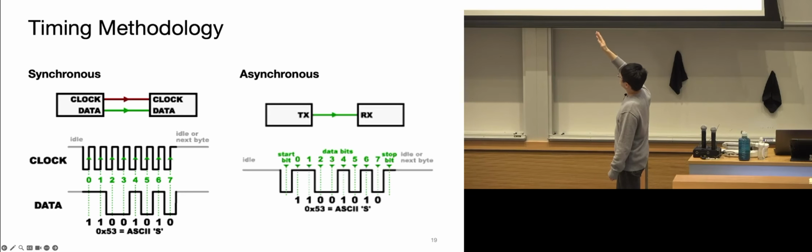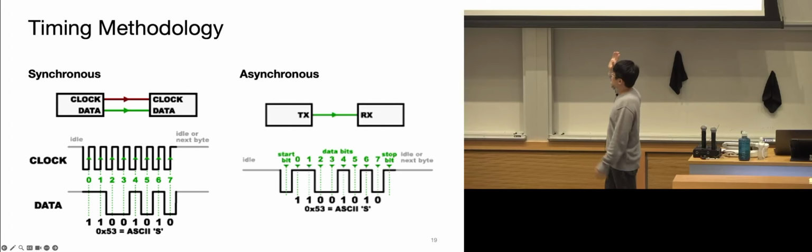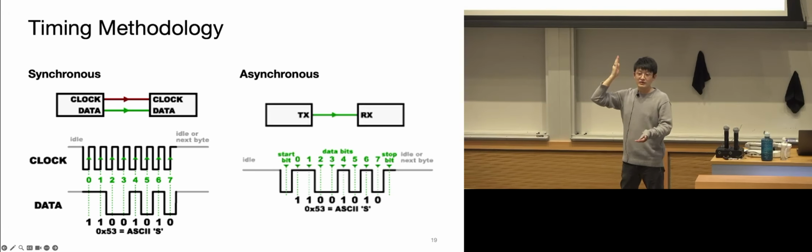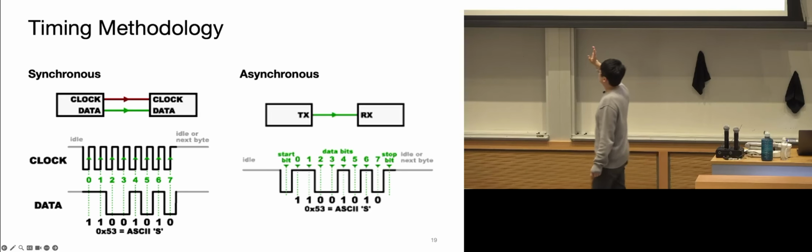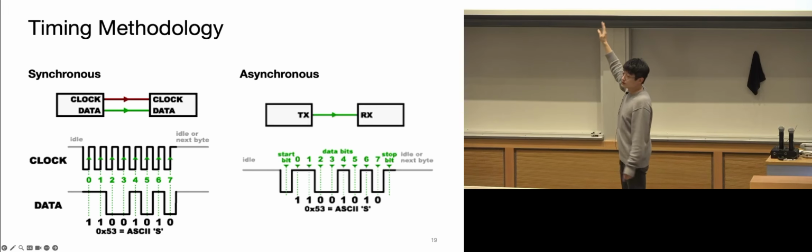And then they usually have some sort of agreement on what the start bit looks like, and what speed they should use to clock the incoming data stream. So by default the line stays idle, and whenever the receiver side detects a start bit, it will be ready and start to clock in the data.